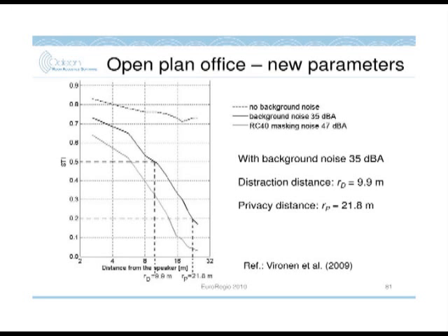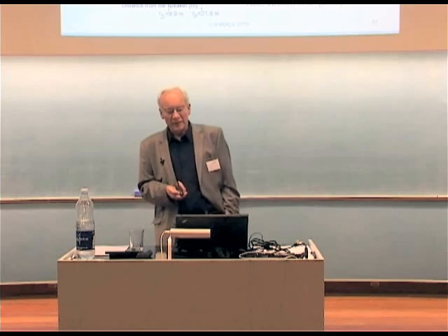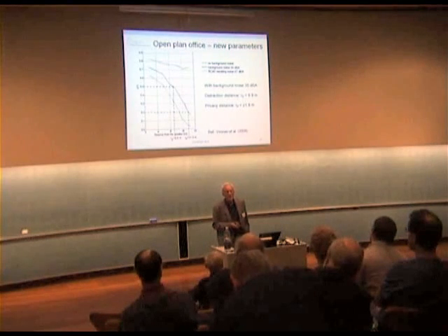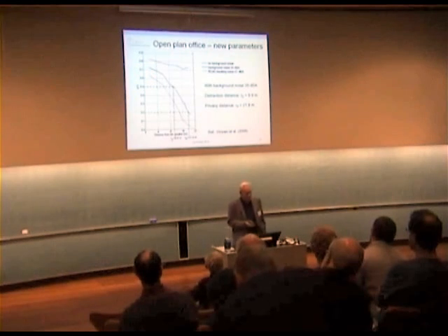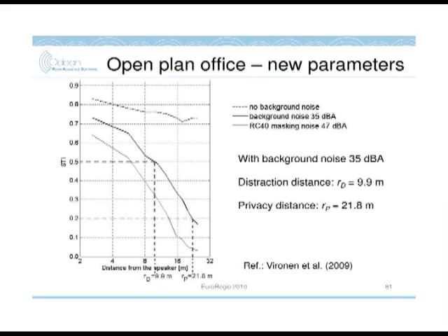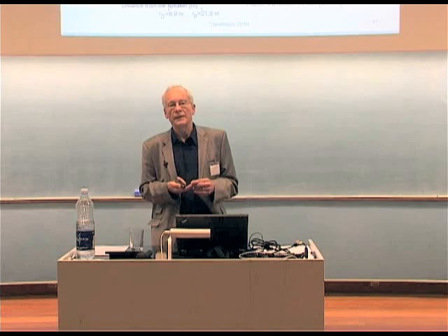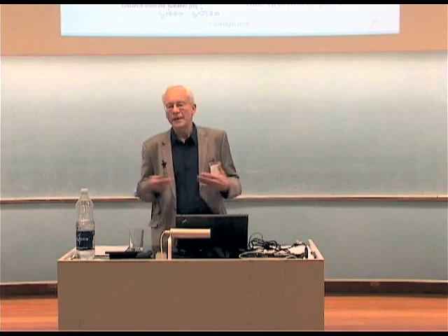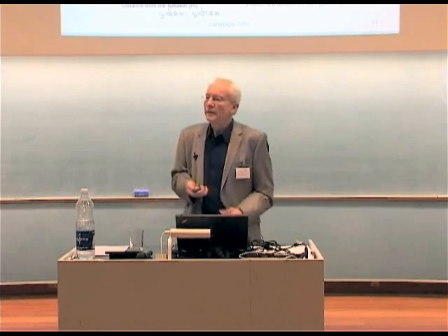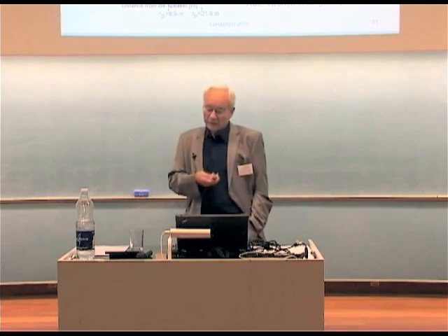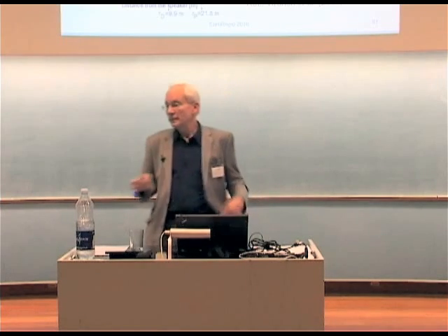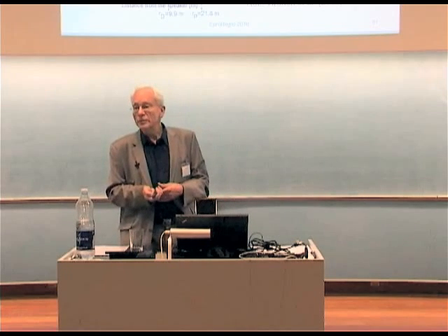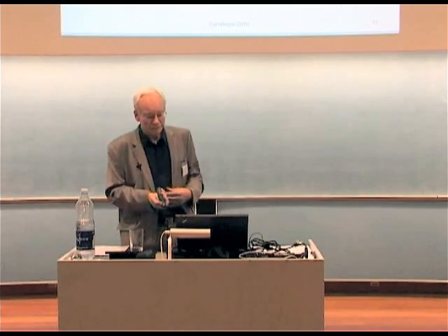And one of the good things or interesting things in using the STI for this purpose is that STI involves the background noise as well as the reverberant field in the room. So both reverberation time and background noise go together into this measure. And this is very relevant for open plan offices because both can be used to improve the conditions.